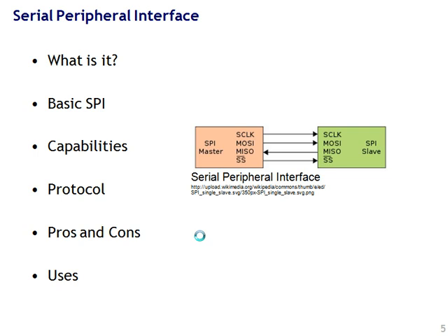Now we compare against what I'll call the master-slave relationship of the serial peripheral interface. First of all, it's not 2 wires anymore. It's now 4 wires. That's a big deal. For short distances, it's not a big deal. But if you were driving cables between buildings with 4 cables instead of 2, it's big. It doubles the cost of everything.